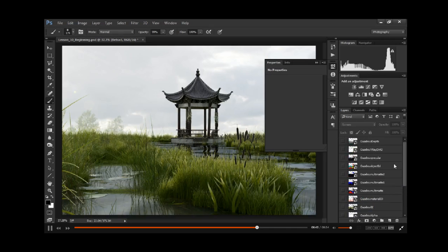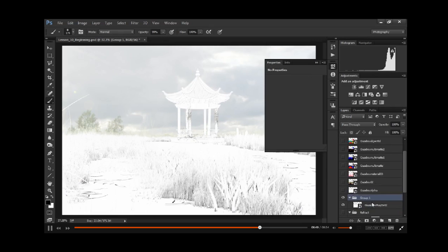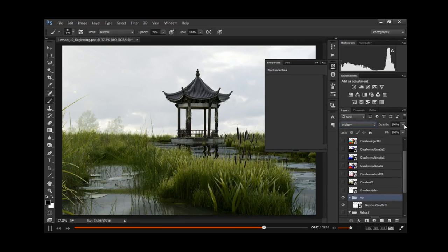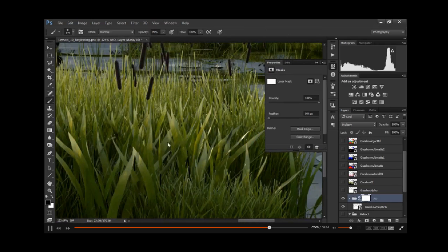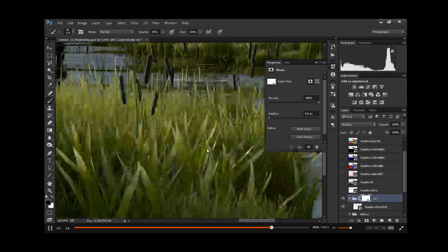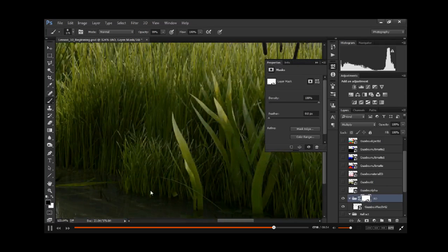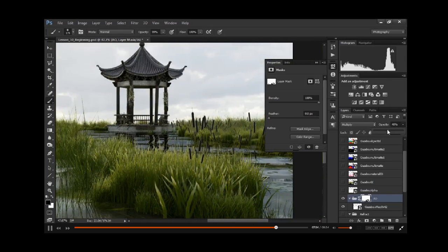Okay, so let's see what else we can start with here. Our V-Ray dirt is going to be a nice one to do as well. So what's nice about the dirt, I'll just name this AO. We're going to multiply this through. We don't necessarily have 100% opacity on this one. We just want to bring in a little bit of it, but we have to watch for, and I'll start with 100 just so we can see it, the areas where there's too much occlusion going on. So I'm going to mask this and just start painting away from those areas that have maybe too much. There's a few here. And then there we go. So those areas were just a little problematic. And then we can start cutting back the overall effect of the occlusion.